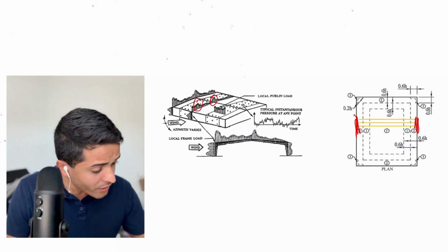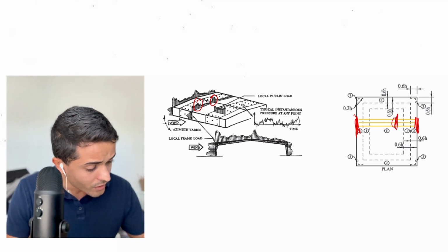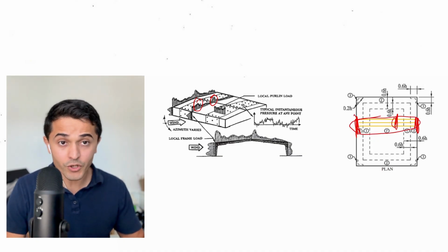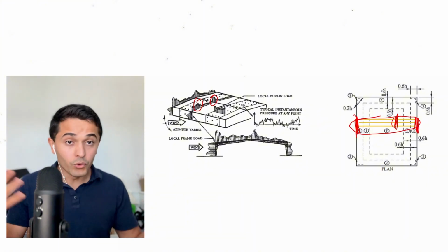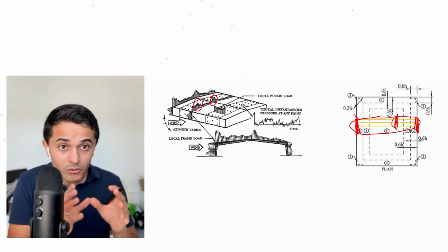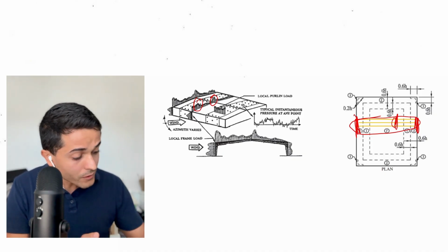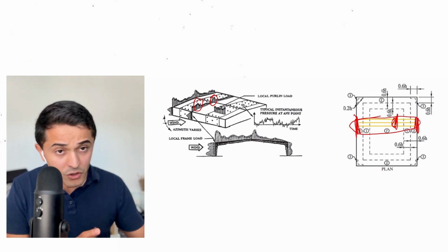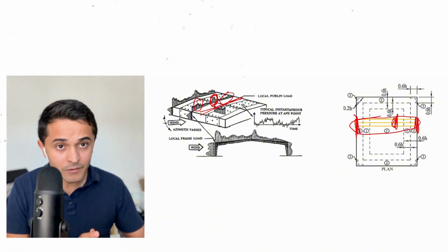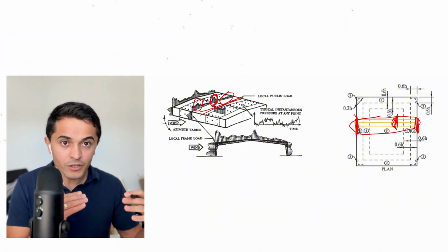Guess what? You may have a hotspot right here, but you're not going to have a hotspot encompassing the entire portion of the building. Through wind load testing, they found that the way they're going to categorize that is by dividing them into zones based on the geometry. But in zone 1, you may have a hotspot here, and the other locations will be, let's say this is my truss right here, you may have a hotspot where I indicated, but then lower pressures on the other areas, so it kind of averages out.